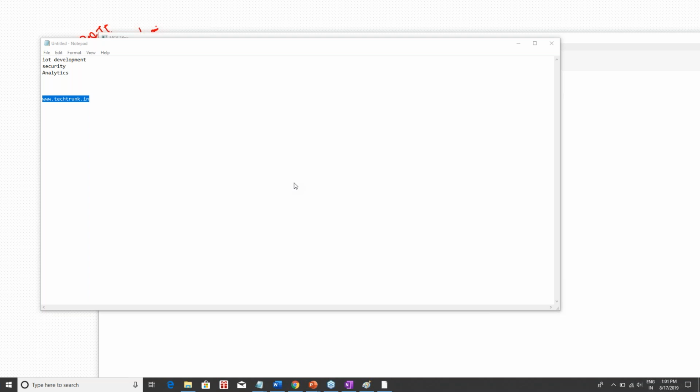Okay, so Zigbee, NFC, and LoRaWAN, Sigfox. These are different wireless networking technologies. Zigbee is also a kind of gateway-based system. Like LoRaWAN, there's one gateway, and there are different end nodes which can be interfaced with the microcontroller and connected to the Zigbee network.